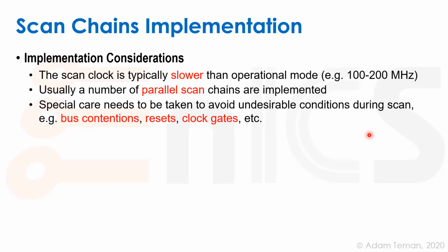I'm not going to go into how to deal with them, but in general, Hanan and some of you others have seen that a clock gating latch has a test enable signal, because this automatic clock gating we want to completely disable when we're in scan. So once we go into scan enable, we're always going to pass the clock through. There are also problems with multiple clock domains. We have to make sure that they're all getting a clock at the same time, unless we put different scan chains in different clock domains. There are a lot of these implementation problems that give people headaches.